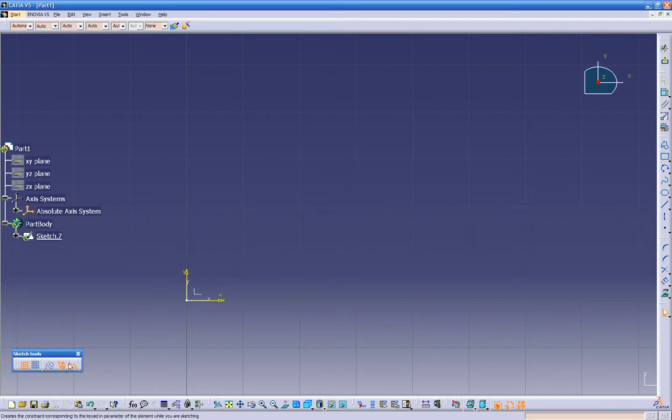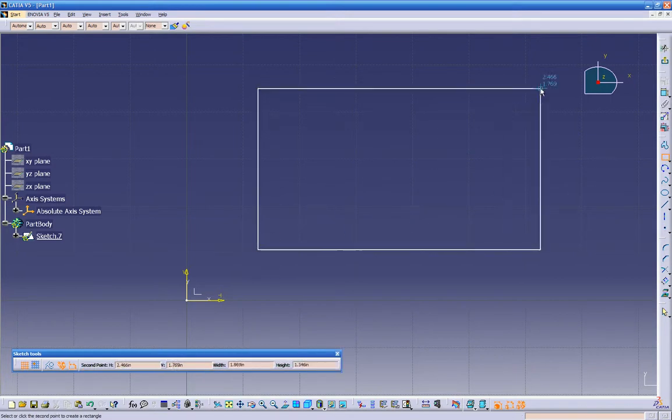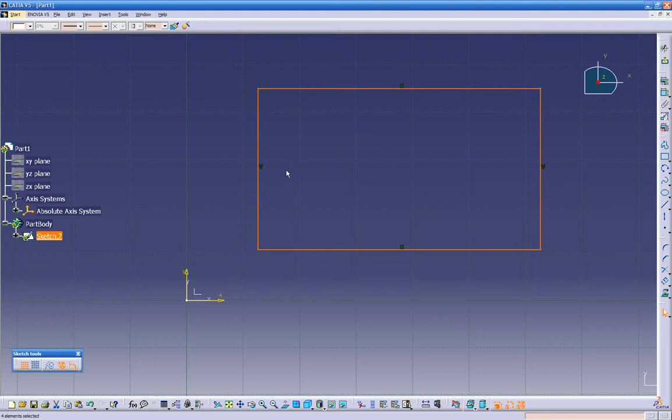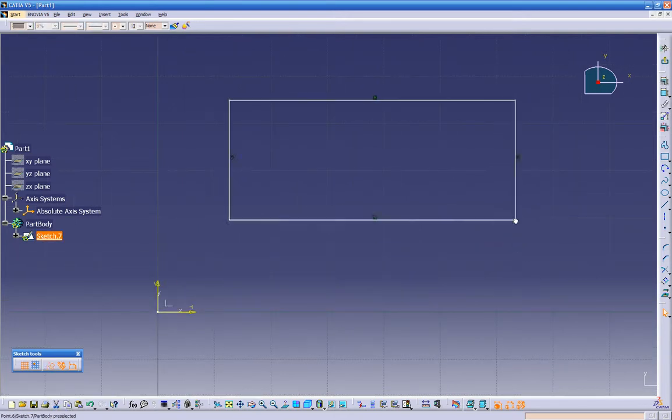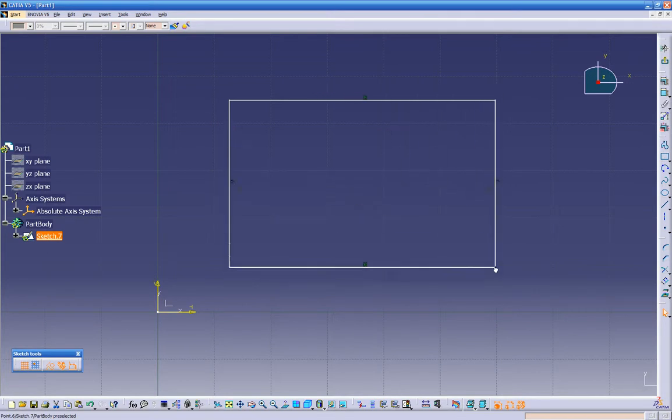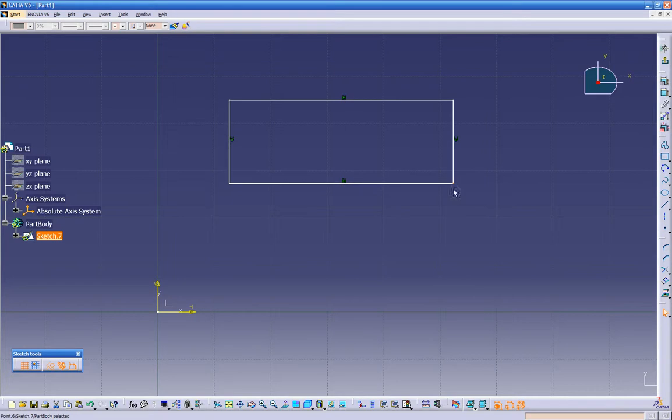So usually, for my preferences, I like to have both of them activated. So in this case, once you're going to create a rectangular, it automatically knows that this is a vertical line, horizontal, and horizontal. And if we try to move it like the previous rectangular, we cannot change it. So if we deactivate this option, we create another rectangular. Sorry, let's deactivate this. Give it one more try. Create another rectangular.